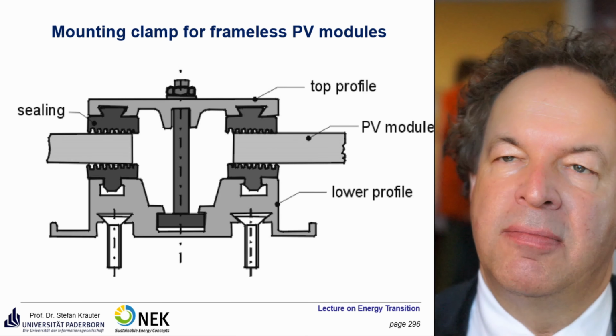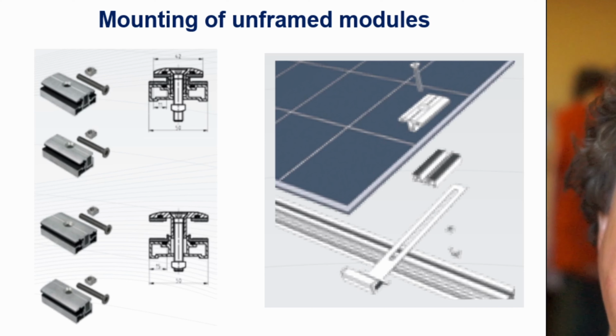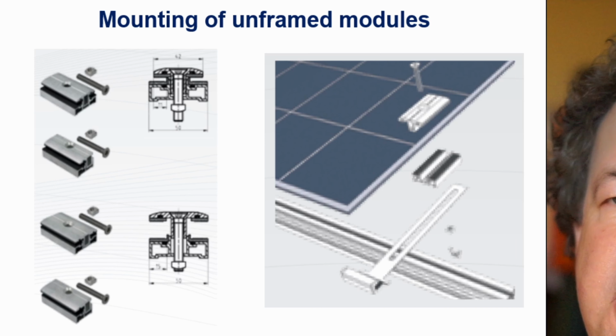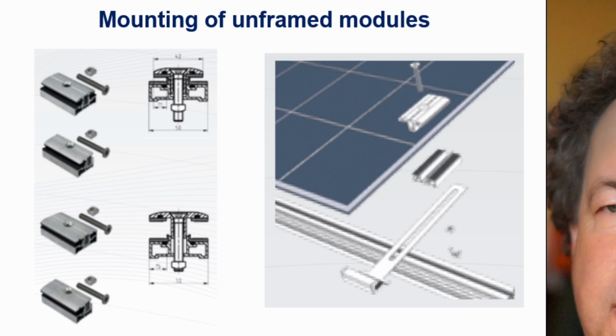Here you see some examples available in different sizes, in different area. It's important to obey the requirements of the manufacturer of the modules, from the area of the clamps to the position of the clamps, because sometimes high wind loads could lead to breakage of the glass. So usually frameless modules are quite sensitive and you have to install more cautiously.